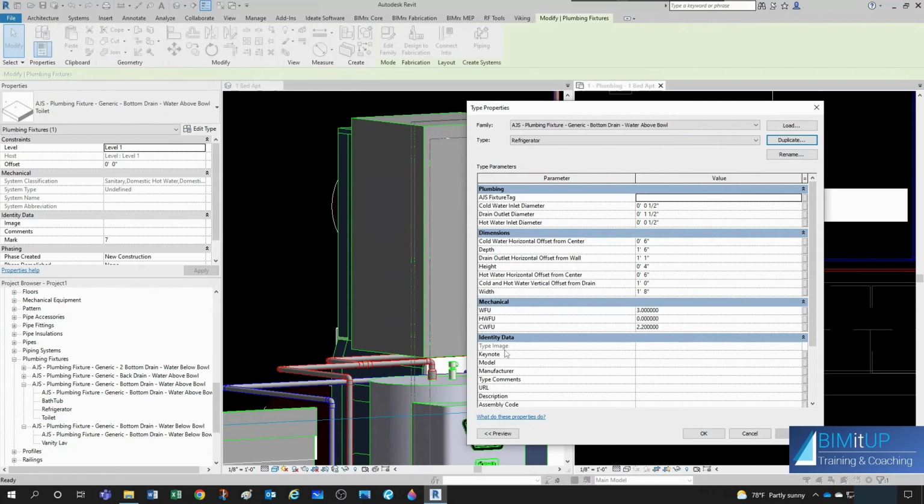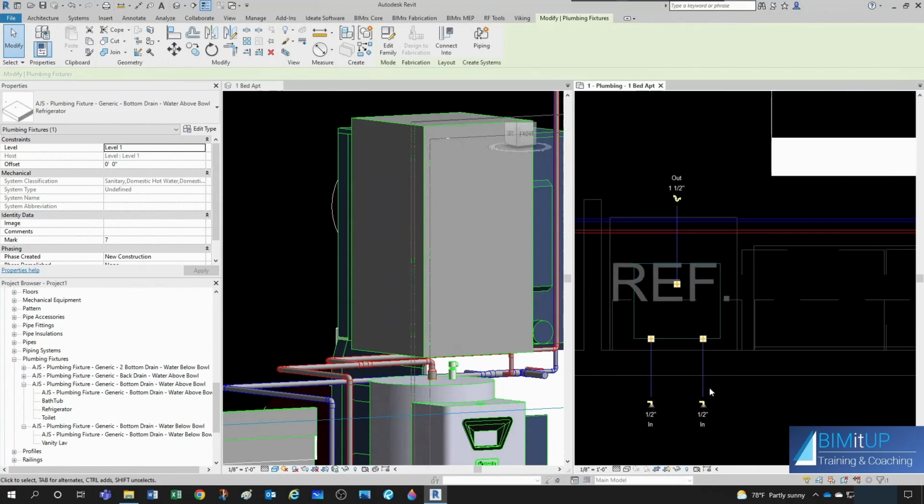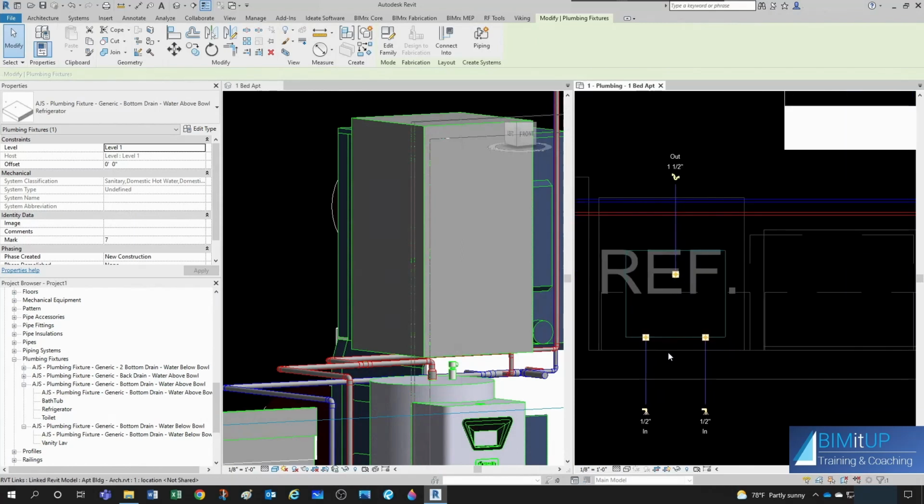And then to this one, you actually don't have to take into account the fixture units. It definitely doesn't have any waste. It doesn't have any hot water. It has a little bit of cold water, but we can just disregard that. It's so small that it would be insane to take it into account. We're using Hunter's curve anyway, so if you want to know more about water fixture units, check out the video on Hunter's curve, and I'm going to do another video going deep into Hunter's curve. But for now, all we care is that there's some cold water here, right?